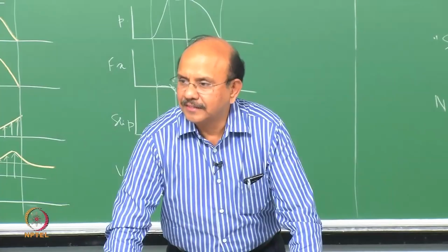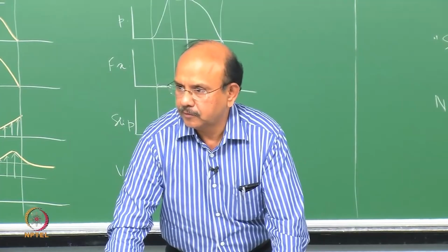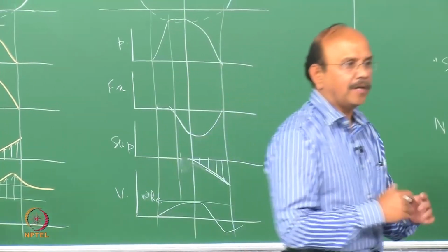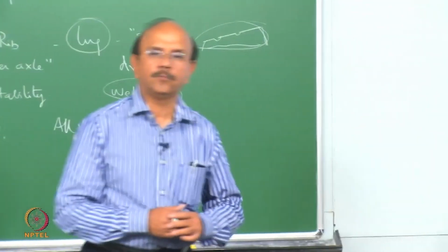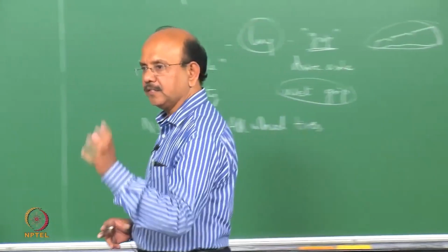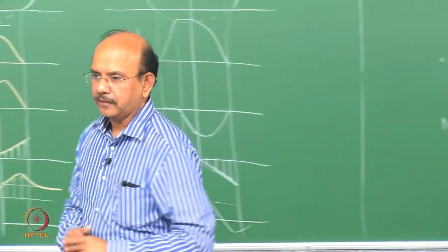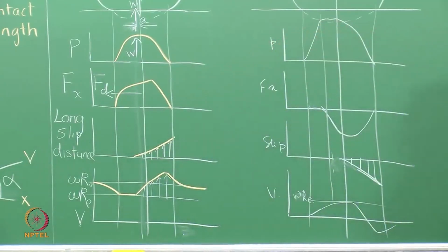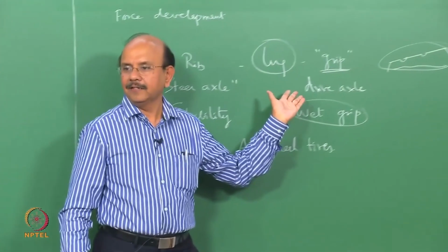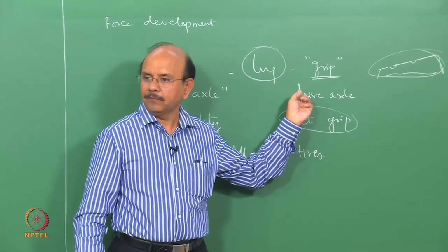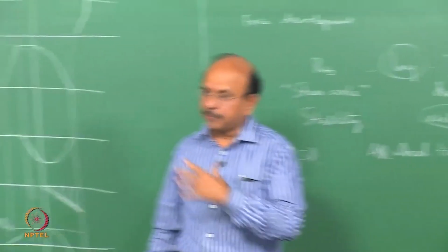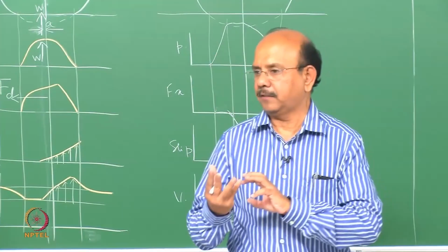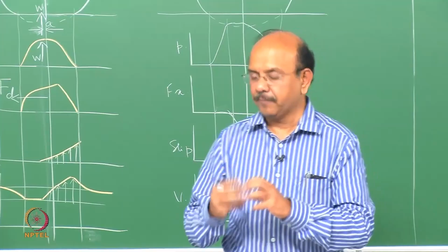And so the tires are usually rotated from one wheel to the other. There's what is called a rotation plan, which the vehicle manufacturers or, more importantly, the tire manufacturers give you, so that the tires are rotated. This can happen in lug tires as well, right? Yes. Usually the lug tire, since it is at the rear, you do not have this problem. So you have what we call a semi-lug tire, or a hybrid tire between a lug and a rib.